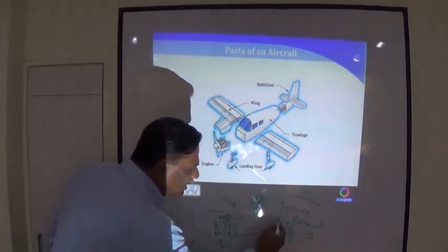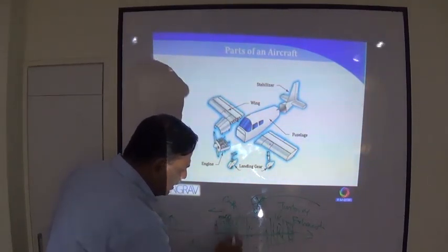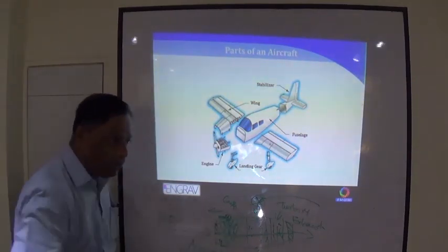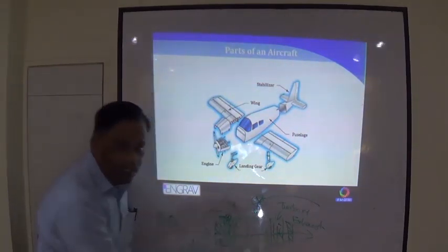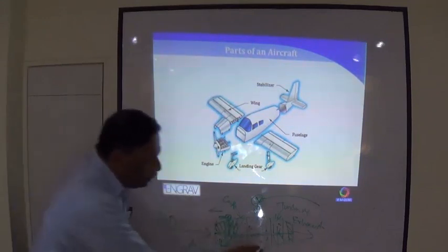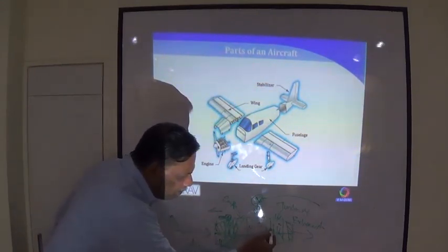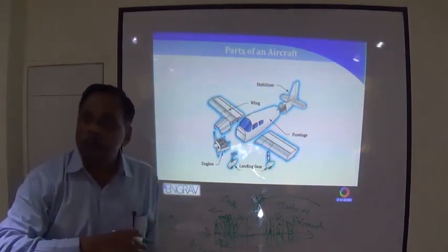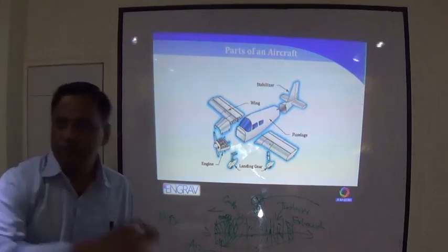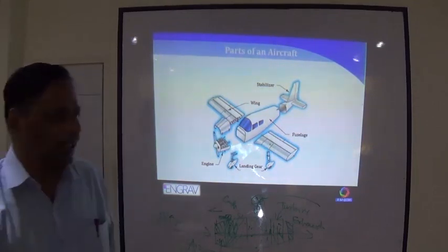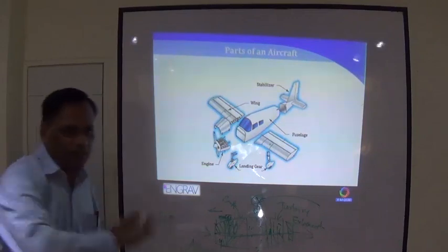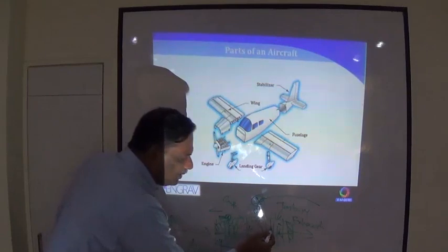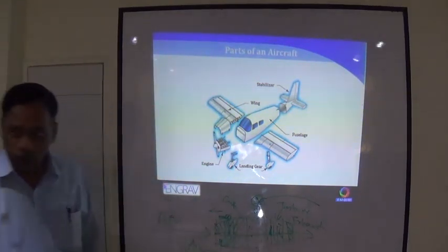And these blades are in different stages. You'll have compressor first stage, second stage, third stage, fourth stage. Bigger the engine, you will have more stages. Turbine, first stage, second stage, third stage. Let us say this turbine blade is made of alloy. With every start it goes through a thermodynamic cycle. Forget about 10,000 degrees, take it only as 2,000 degrees. With 2,000 degrees, every cycle you go through that. So the amount of thermal stress on a turbine blade is huge.